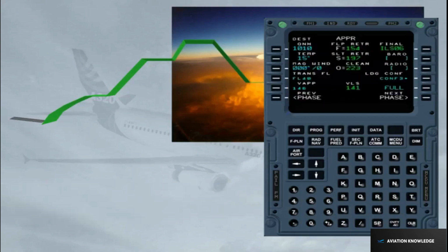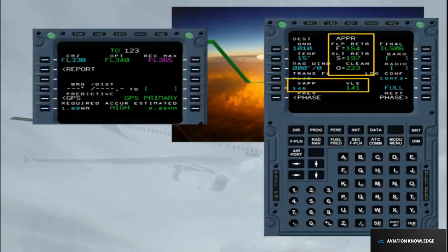Additionally, the optimization function provides the following data: maneuvering speed for takeoff, approach, and go-around, OSF. Approach speed and VLS in landing configuration. Optimum flight level and recommended max altitude. The optimum flight level is the one at which the aircraft incurs the lowest cost for given flight plan, GW, and CI. Note, these terms will be discussed in more details in the performance course.